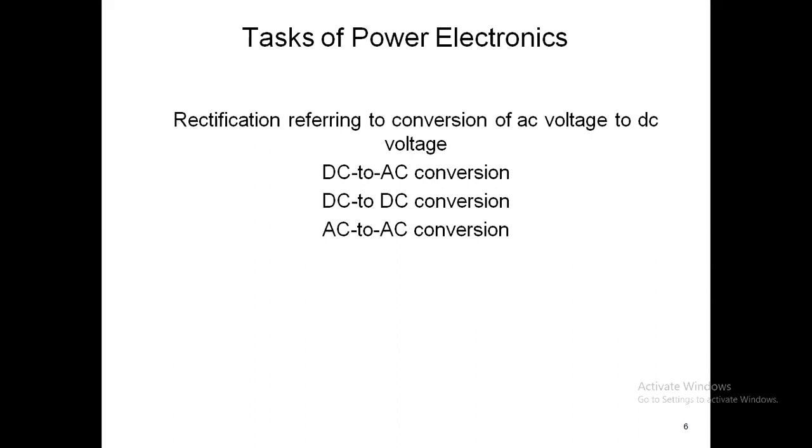So voltage ripple is decided by this capacitor, and the current ripple in the output is controlled by the inductor. So you have to choose some inductor for that design so that the current ripple does not go beyond the limit. So you have to find out the value of the capacitor and the inductor. In the design problem you have to find out these kinds of things.